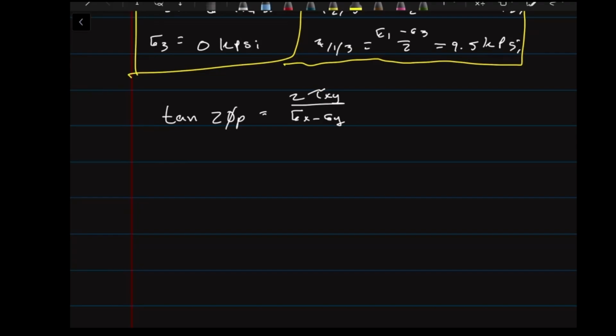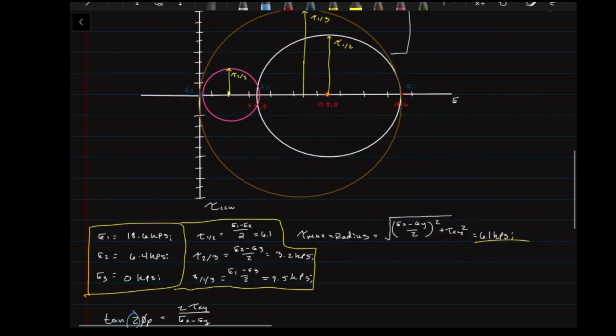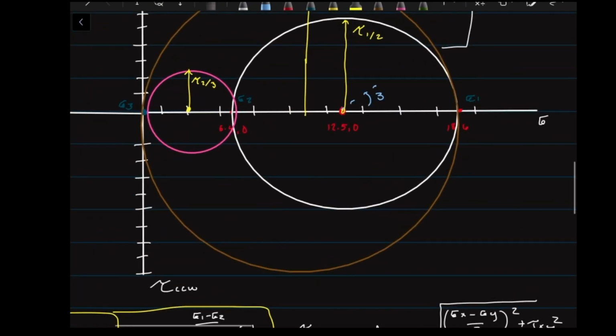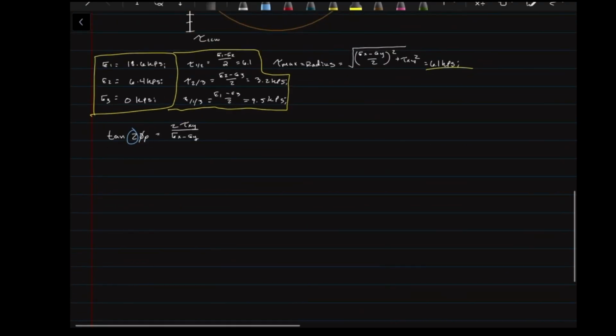Now, this is very nice. Remember, what is this 2 here for? Do you know why this 2 is here? That's okay. I can tell you. The difference between Mohr circle and reality, there's a difference, believe it. The values in Mohr circle are double what they are in reality. So if you were to get an angle right here of 30 degrees, and then you came back out and you said, let me do the plot, this would be 15 degrees. So remember, you must divide by 2 to get out of Mohr circle and multiply by 2 to get in Mohr circle. All right, let's keep going.